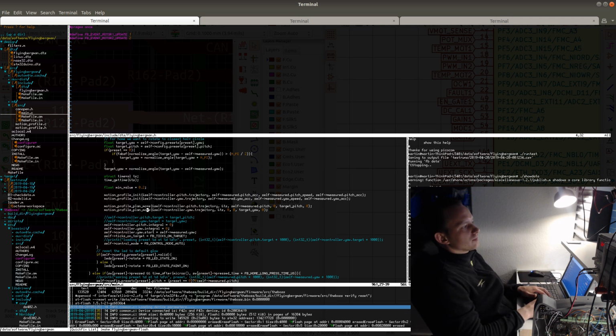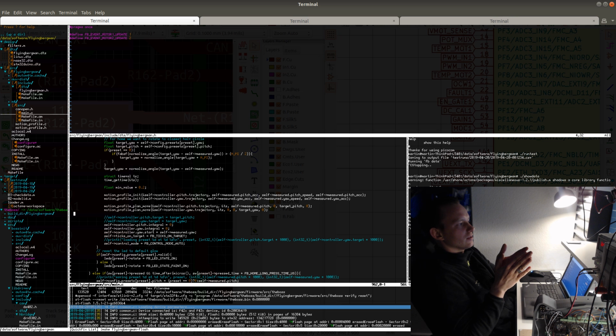But in this case, I just easily prevent that problem by planning around the 0 point. For example, you could have an angle that starts at minus 3 and then goes to 3, right? And it's going to move through the point where it goes from minus pi to pi and then down to 3 again. If I plan from 0, I avoid that problem.